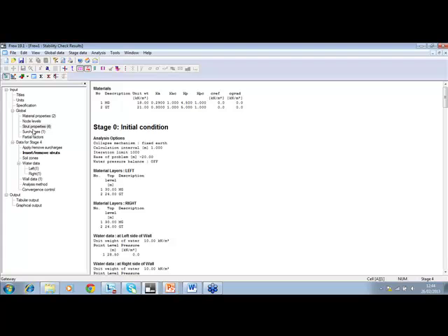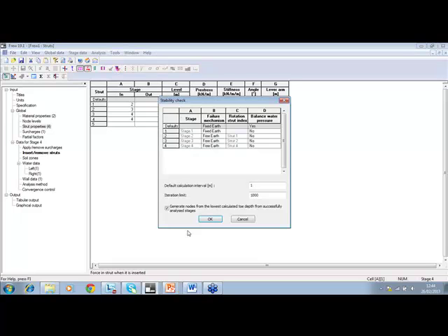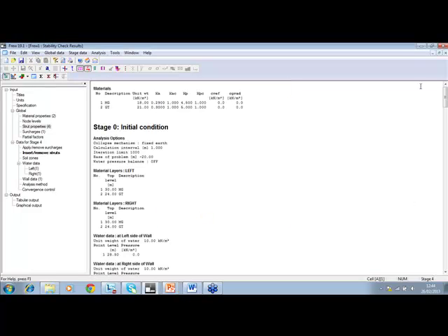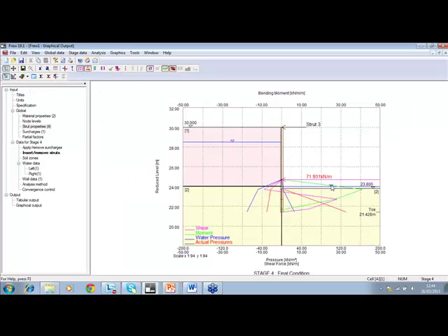So what I will be now doing is looking at the strut properties and cancel the analysis. And actually, we'll say, okay, the basement is acting at around 24.7 meters. So the basement level is 24.7 meters. I'm going to run my stability check, the outputs to see toe level. If I wanted, I could also look at the graphical output. Okay. And again, I'm going to generate the nodes.